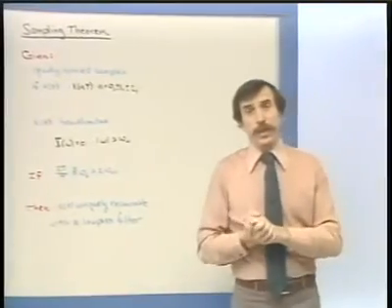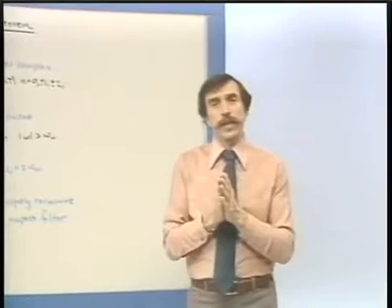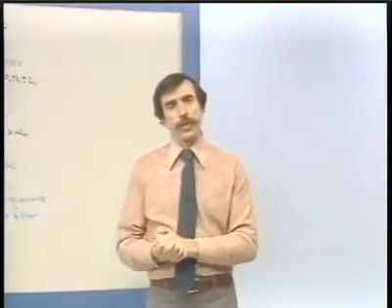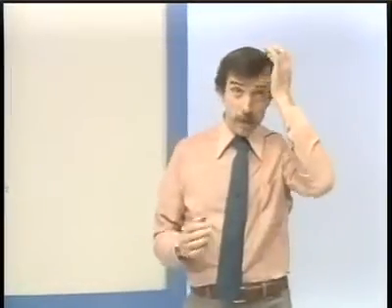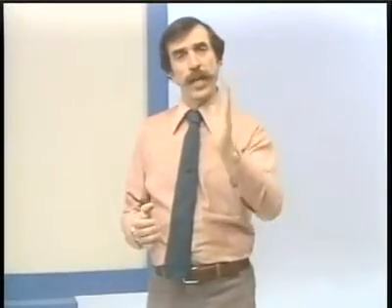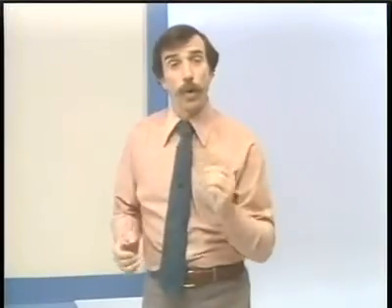Now, the sampling theorem is, I would say, a watershed or cornerstone of a lot of the discussion that we've been having, for a whole variety of reasons. It first of all drops out almost as a straightforward, obvious statement. But more importantly, what it says is that if I have a continuous time signal which satisfies the right set of conditions, I can represent it by what it does at sampling instants, or equivalently at discrete instants of time.